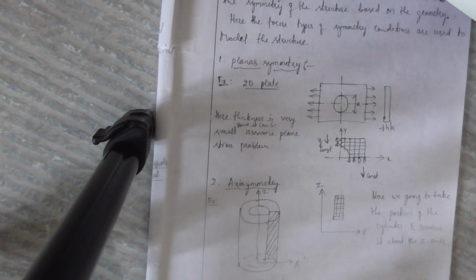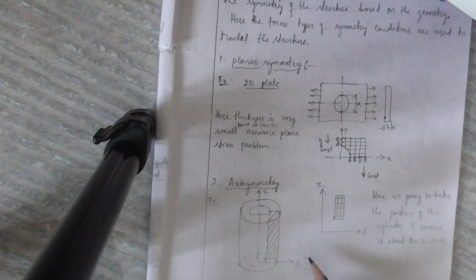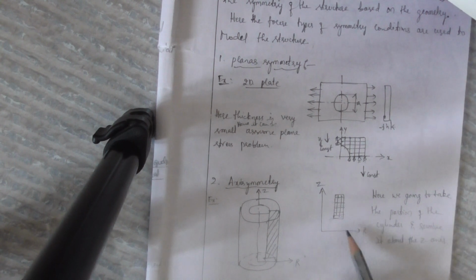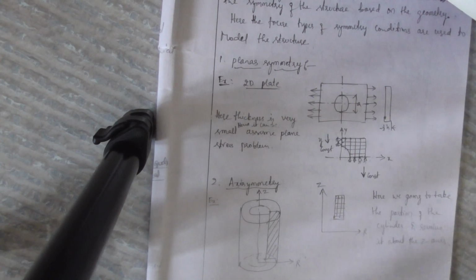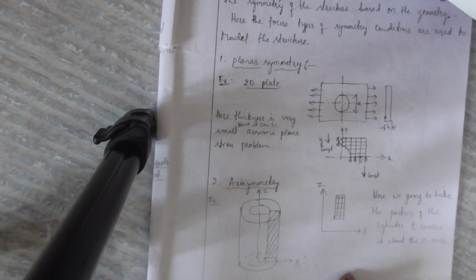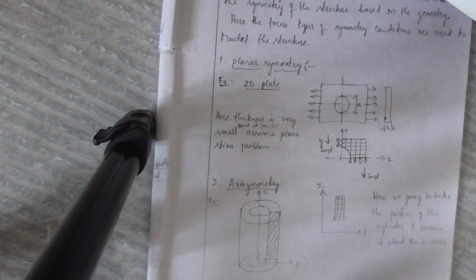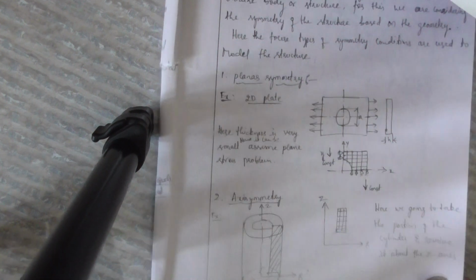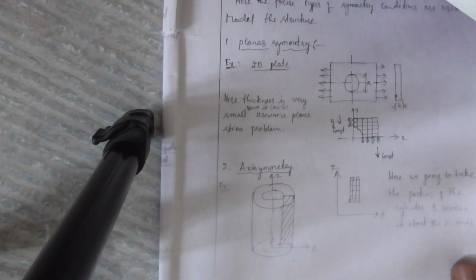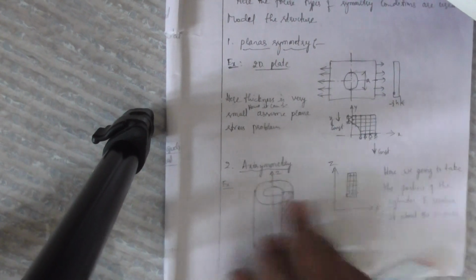Then there is an option to revolve in ANSYS, or in any kind of FEA software, so that you can get the entire cylinder and you can get the behavior of the cylinder subjected to some internal pressure or any load like that. So this is called the axis symmetry. One more example is this, the axis symmetry cylinders.